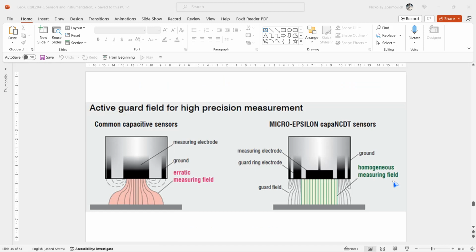Capacitive sensors offer the possibility of highly accurate distance or displacement measurement, for example in a controlled XY table. A capacitive sensor designed for product inspection: the goal is to measure the inner diameter of cylinders using a coordinate measuring machine with touch probe. In this work, the bending of the touch probe or a thin stylus is determined by capacitive means. The method allows measuring an internal diameter of less than 0.3 millimeters with an accuracy of 1 micrometer.